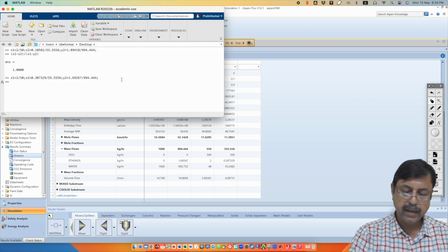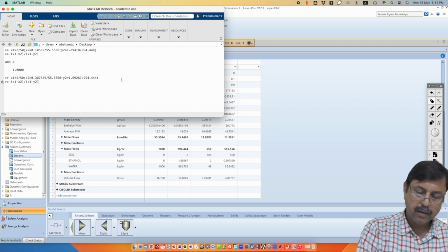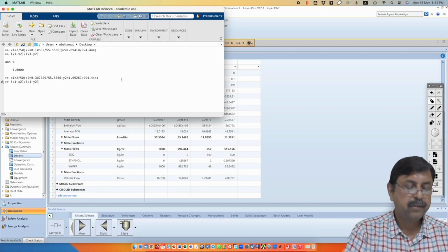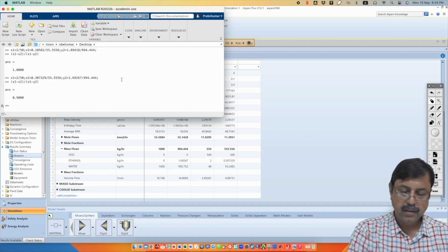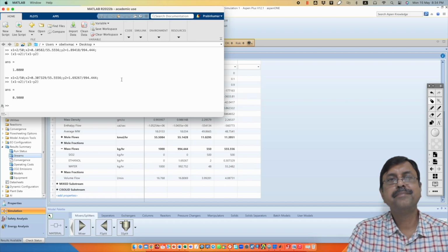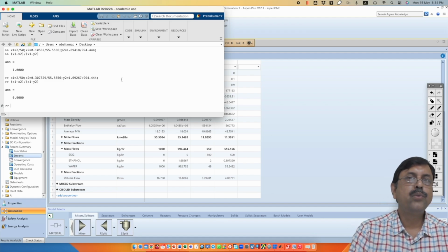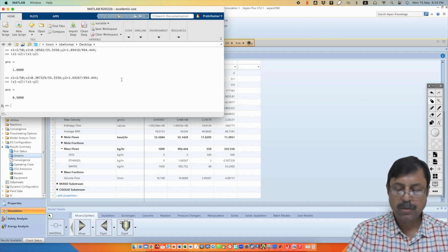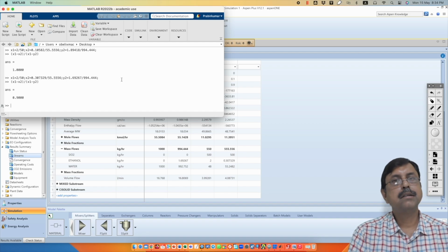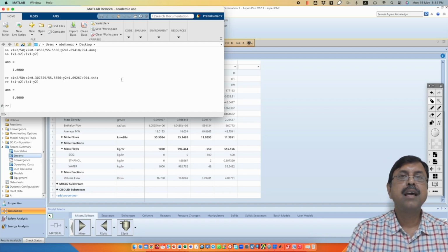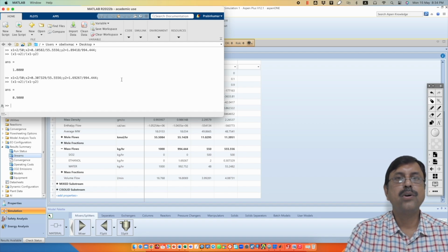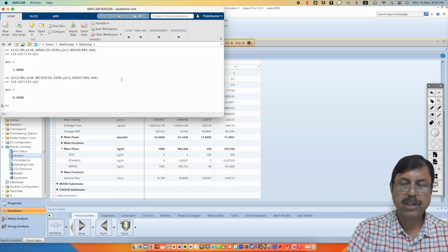So we have redefined x1, x2 and y2, and then find out the efficiency, mixing efficiency. You get 0.9. Okay. So that's how the liquid to mass ratio and mixing efficiency has to be set for a single stage washer.